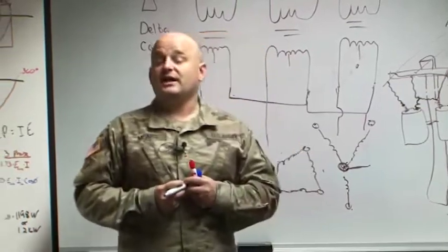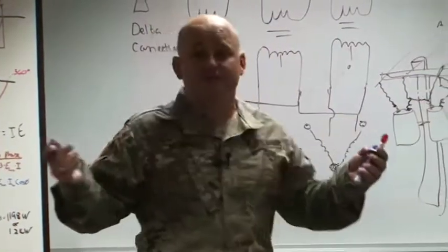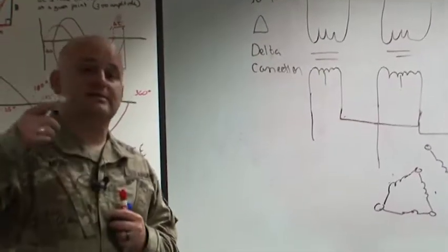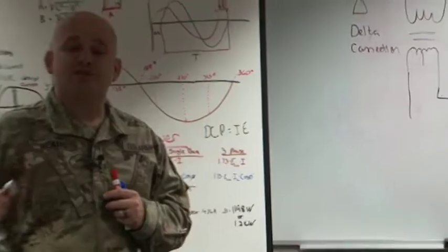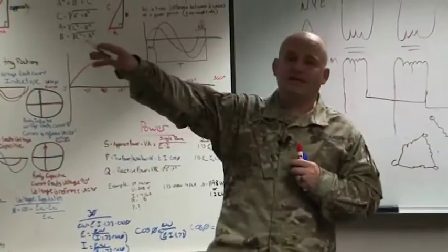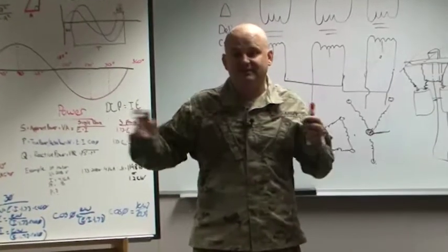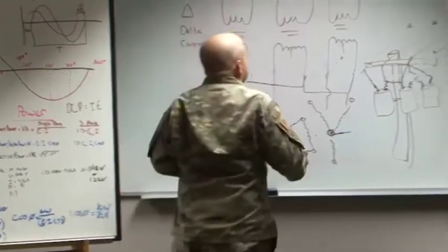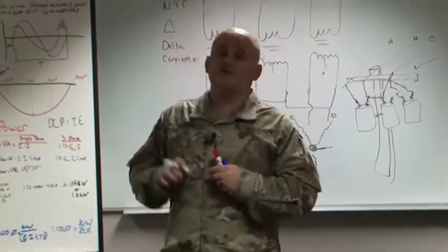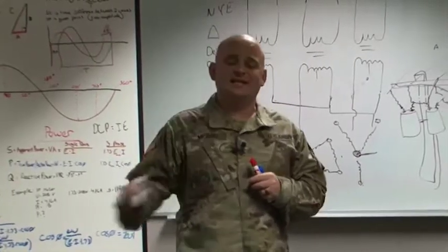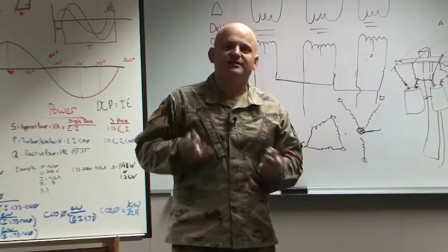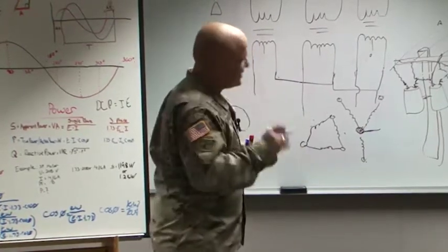But say you have a place that's most normal places, let's say this classroom, and we know that we have 120 volt loads all through these floors, but oh, by the way, we've got this giant AC system over there that's running off 208 volts. So we need that larger voltage for this bigger equipment that we have over here. So we have to have that voltage range. So then we'd know we'd have to do a Y connection. Now there are some instances, and we're not going to go into it, about different delta configurations that you can do to actually get that secondary voltage. However, those are not going to be a commonality for you. What's going to be a commonality is a delta connection or a Y connection. So I'm just trying to keep it simple.